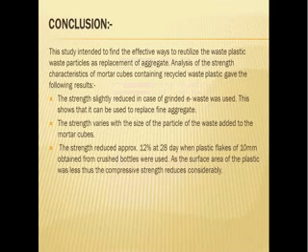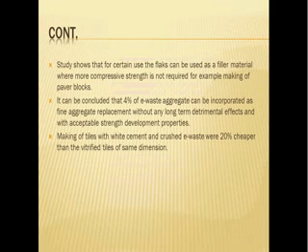So the plastic bottle waste can be used in some structures, like making paver blocks, where substantial strength is not required. It can also be concluded that 4% of electronic waste aggregate can be incorporated as a fine aggregate replacement without any long-term detrimental effects.